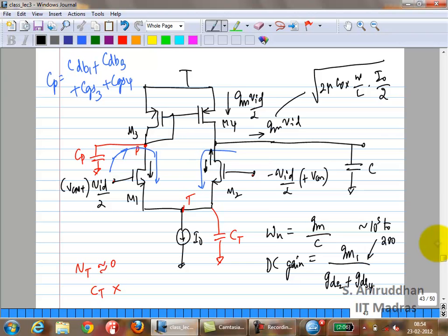Normally, if you want to measure the noise performance, what do you do? You use the input referred noise. What did we do for that? We shorted the output, calculated the output noise current, and divided by the transconductance, right? Isn't that what we did? Or you can find the open loop output voltage noise and divide it by the voltage gain. Either one is fine. Okay?